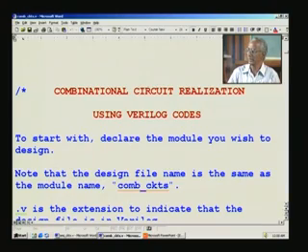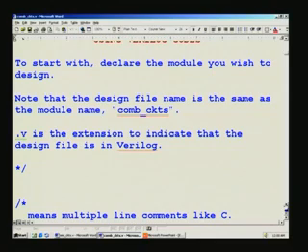We had to declare a module name, and then what is new here now is whatever you have as a module, your design, you will have to ultimately put it into a file, and when you make it into a file, give the very same name that you have had earlier. For example, module_name was the name of the module that you have given for your design.